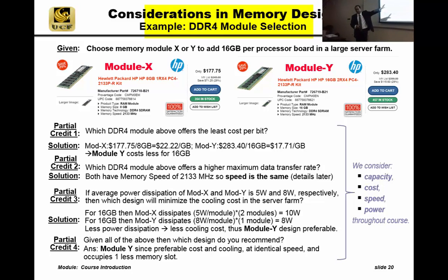You already know watts from physics, but what are the watts that we use? Well, a desktop processor, if you have a pretty fast one, is it using milliwatts, or how many watts do you think? Hundreds. Yeah, hundreds. Like a pretty top-end gaming processor might be 100 watts. TDP is a power dissipation, and if you get much more than that, it's hard to cool it, because watts are actually heat energy. Every time we switch from a 1 to a 0, it means we're crunching bits, we're making decisions. There's some waste. What does that mean? It turns into heat.